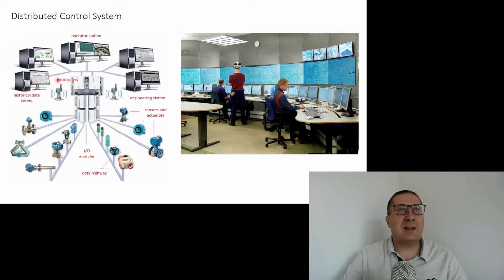He also can add some bias to this set point for pressure, right? So if he's not happy with the pressure, if it's still too high, he can also lower the set point for this pressure and stay with the automatic mode, hoping that the control system will do its job.